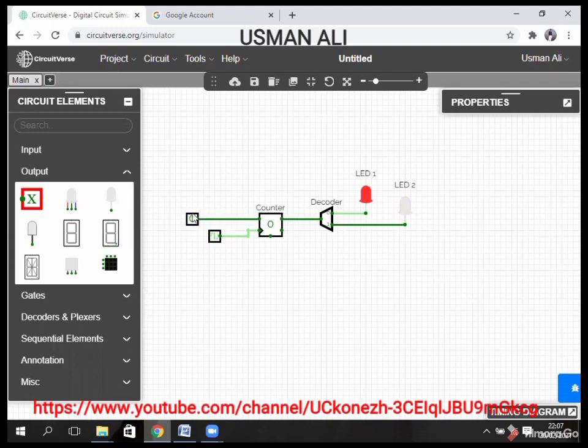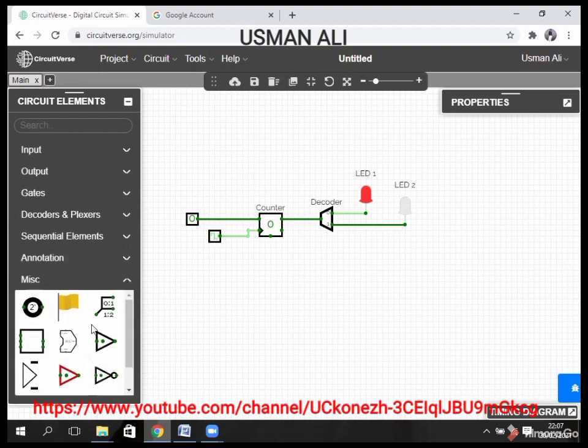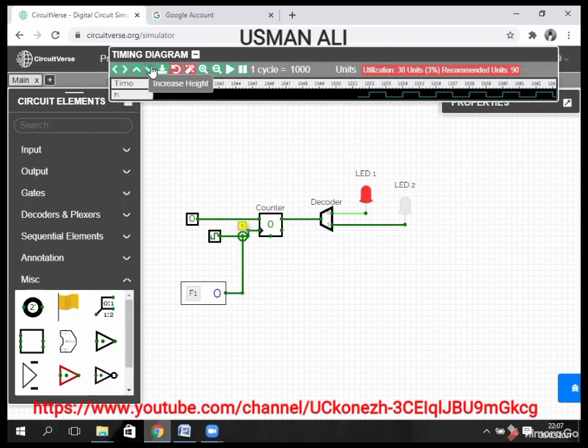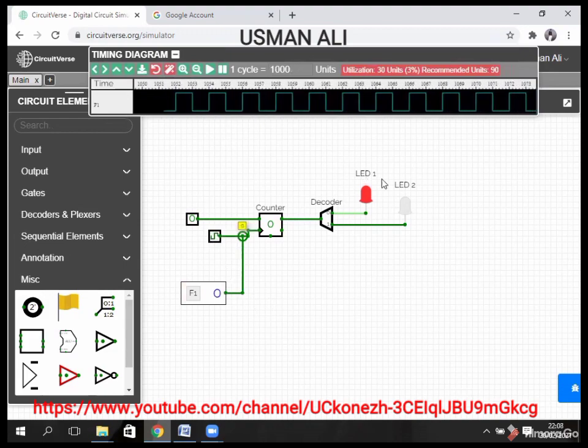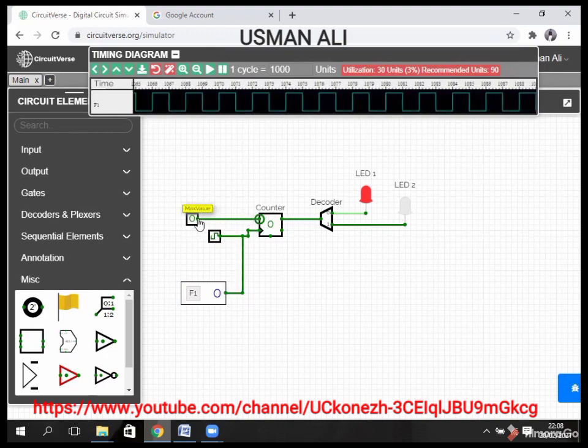Because our max value is 0, it means only one number can show, and it is our first LED that lights. In our counter, the clock is on and it's changing its signal. We connect a flag here to show you the clock is changing its signal. You see it here, and we point to the timing diagram and modify it a little bit. You see here the clock is changing signal, but there is no change in the output. It is because of the max value, which is 0.